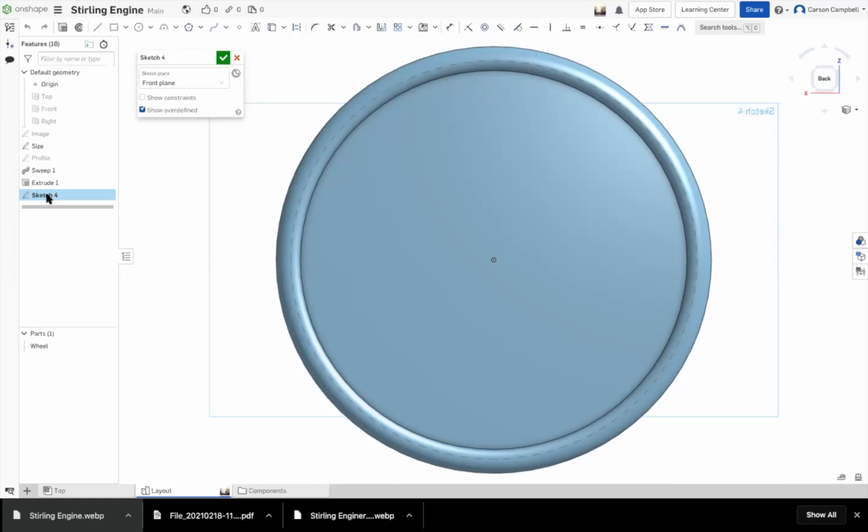Is that anything related to parent and child? Yep. So the references have orders, and once a child loses a parent, that's when things go red. Makes sense. So if I deleted the sketch, the extrude would freak out. Typically when we start with solid modeling, I say to first-time beginners that this system is remembering everything you pick, so you pick wisely. And it freaks everybody out. But with time, you'll figure out what you should be picking and what you shouldn't be picking.